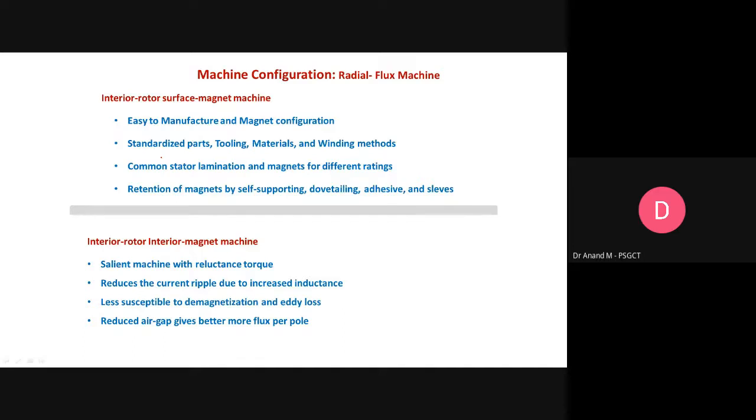If there is high speed, or a temperature gradient exponentially increasing, then wear and tear will cause a problem with respect to the adhesive glue, leading to displacement. That may lead to breakage of the magnets. Maybe we can avoid this by using outer copper-based or magnetic sleeves for mechanical and thermal protection. But the trade-off lies in what application we are going to choose.